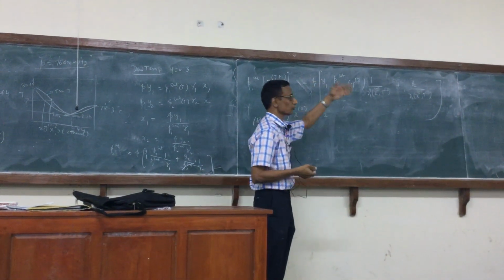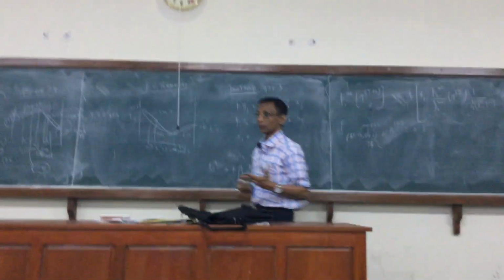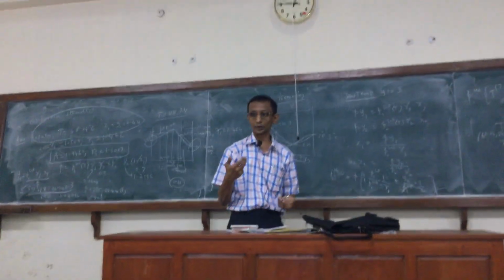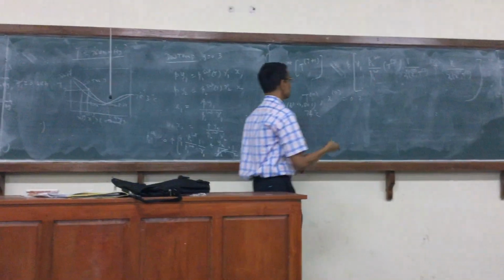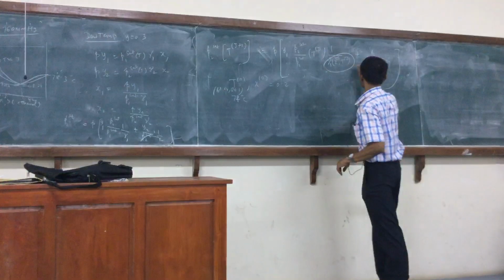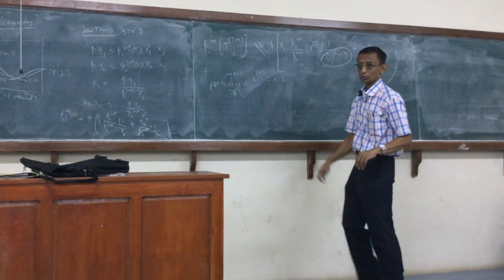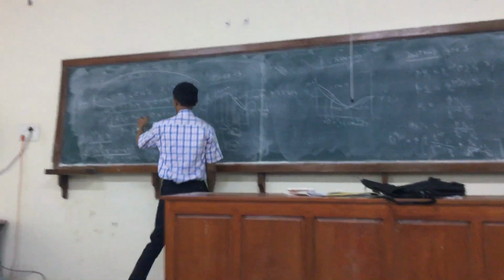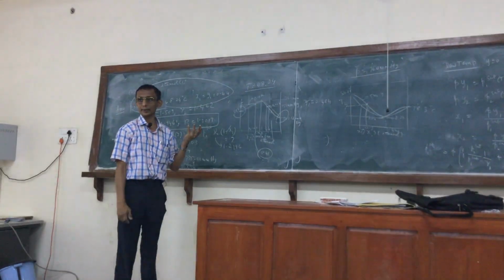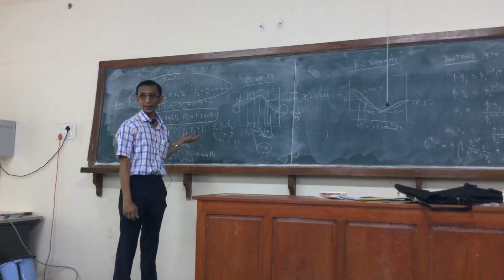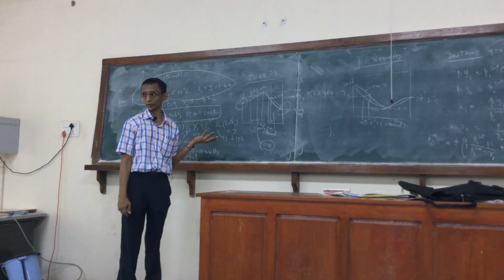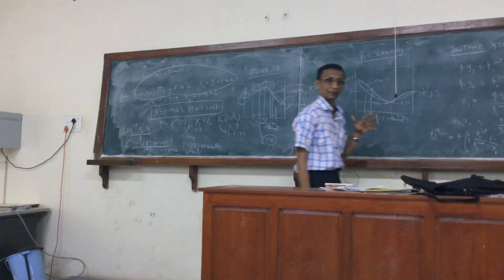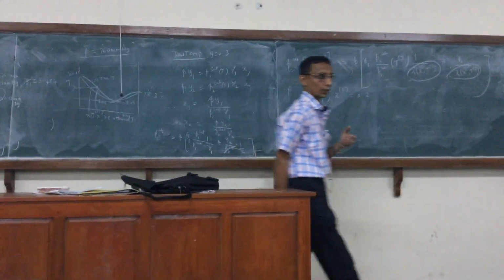Right? And then you just follow the same working that we have done for the ideal case, where we looked at the bubble temperature calculation. Continuing, we have this additional calculation to do. But here we are not assuming any direct dependence. We have calculated these parameters and assume that these are independent of temperature. The A and B, we don't even have to take that into account. In general, A and B are functions of temperature and if that is given,